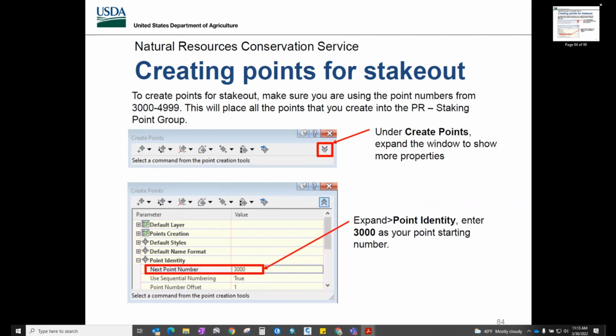and it's off, technically we're held responsible if we stake those out. And we told them, oh yeah, we wrote in the COGO, staked out the elevations, explained to the contractor what the elevations were. If we don't write down in there verified elevation, and contractor to use elevation and double check elevation prior to excavation or whatever, you just want to make sure that you're not telling them that that elevation is specific to what we set, because you could get yourself in trouble on that. So just be careful on the wording on this.